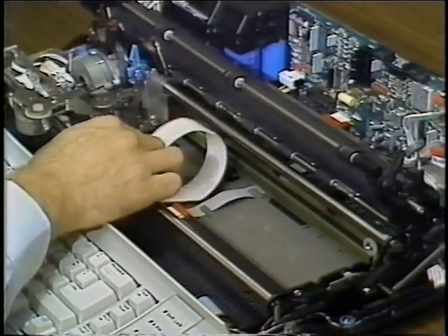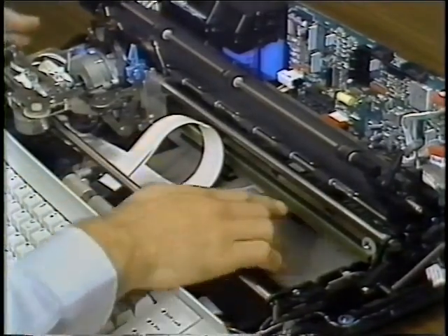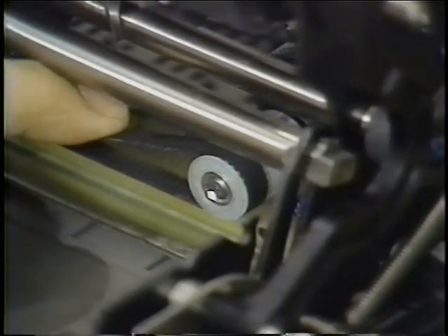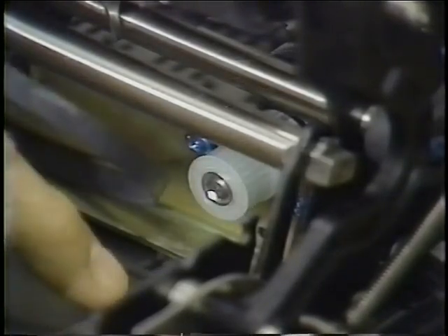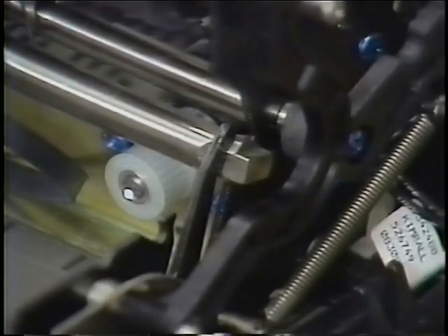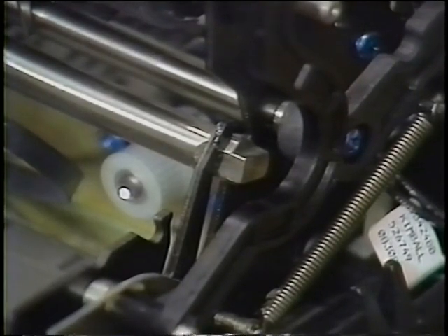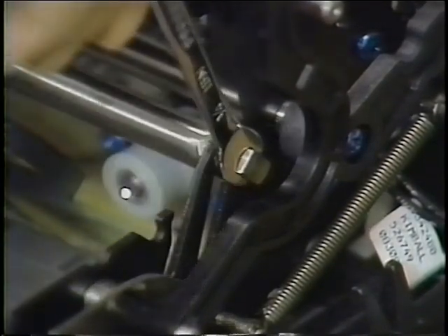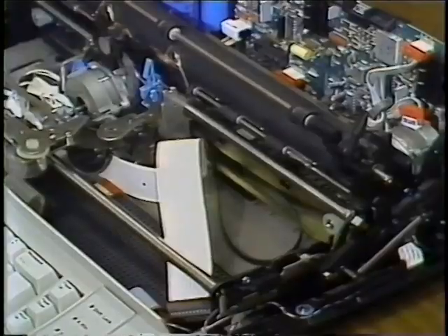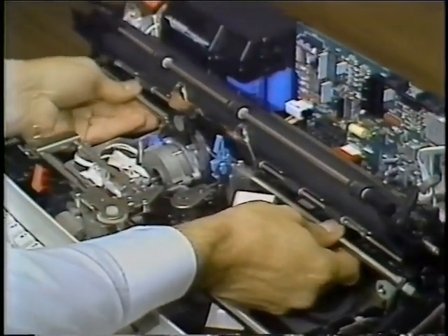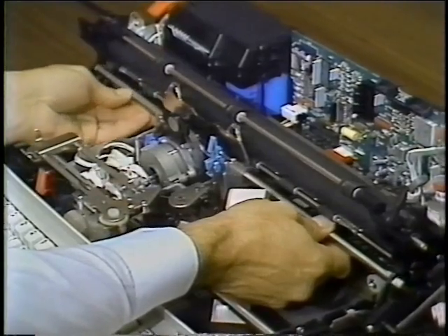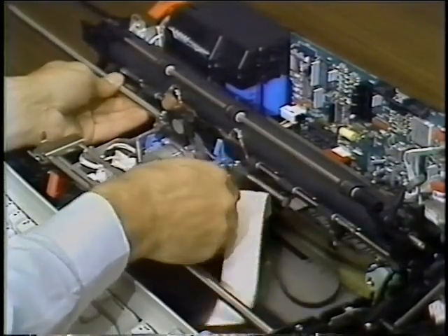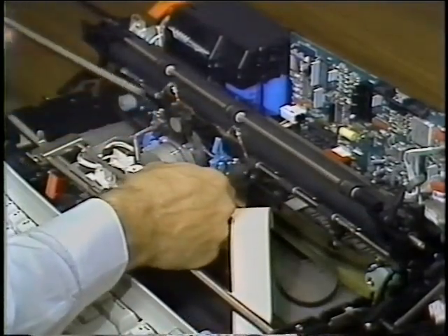Next, roll the transport belt off the transport drive pulley. Do not crease the belt, as this will weaken it. Using a 1/4-inch open-end wrench on the right end of the carrier shaft, turn the shaft top to rear until it stops. Do not force the shaft beyond the stop. Slide the carrier shaft to the right until the left end clears the side frame. Lift the carrier up, and as you hold it, slide the shaft out of the carrier and lift the carrier out of the machine.